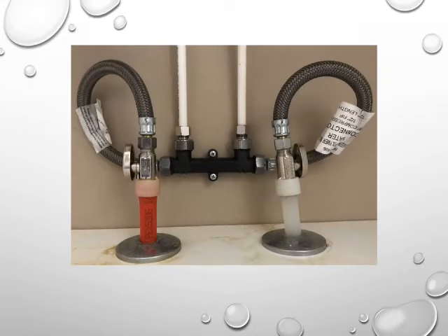So, in this particular setup, it's not a dedicated pipe that's what we call the hot water return line. It's not a separate pipe. This particular system actually uses the cold water side to circulate back through the system. And this is underneath the sink, and typically what you're trying to do is get it to the sink that's the furthest away from the water heater. So you're actually circulating that hot water throughout the house as much as you possibly can.